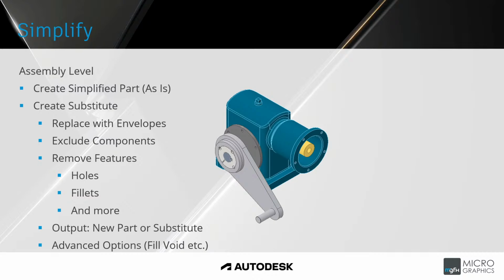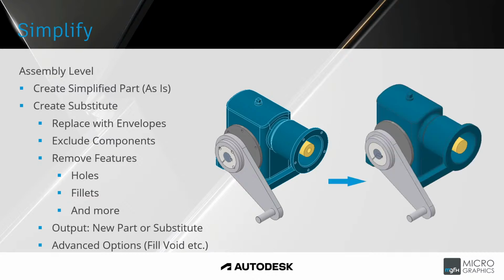We then have the create substitute option, which allows you to either replace components with envelopes. It allows you to exclude components. So we could exclude internal components from the assembly, but it also allows you to remove features such as holes, fillets, and there's a whole list more of features that can be removed. So we can see the difference between the left image and the right image, where the substitute has been created and the holes have been patched and details have been removed.